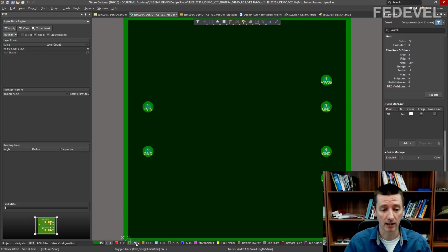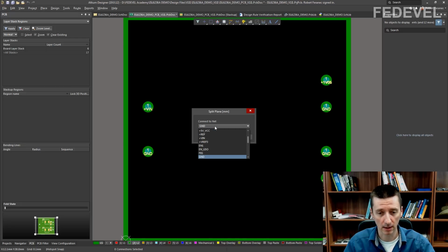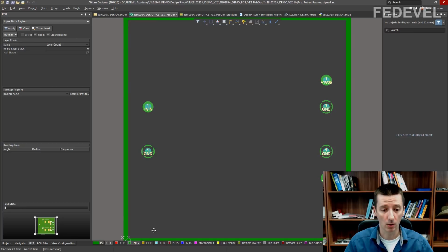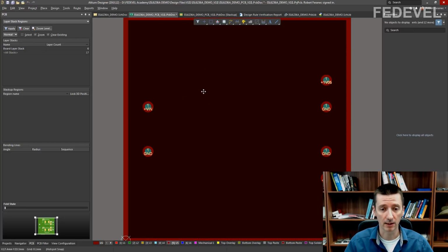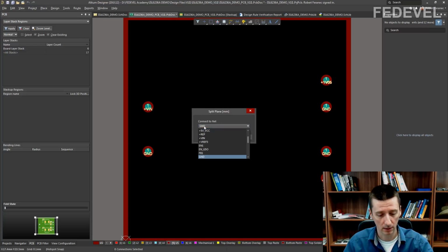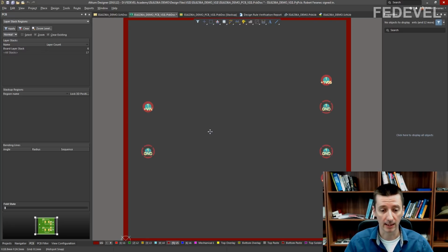So left click on the layer 2, double click on the plane which is on the layer 2. So double click somewhere into empty space on our board and select here ground, GND, left click and OK. Also go on layer 5, double click into empty space and assign ground into our plane which is on layer 5.